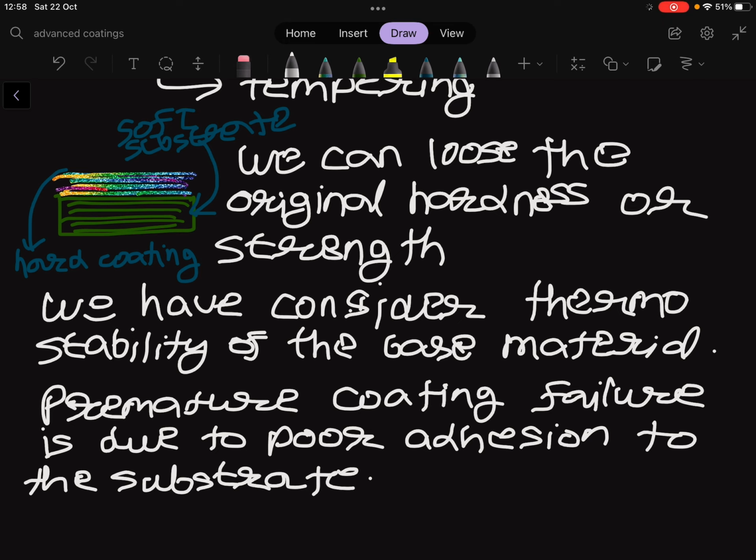So this process typically produces small fragments of our coating. So we produce small fragments over a very hard material in the contact region where components are exposed to large normal stresses. Then we create a three-body wear mechanism, which is very dangerous. So the premature coating failure is worse than the absence of coating, and we have to avoid this process anyway.